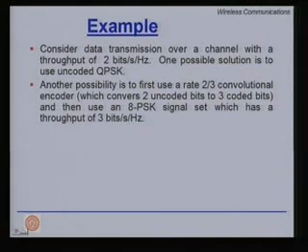If I have done my math correctly, then the advantage gained by coding will more than overcompensate the loss that I encountered by moving my constellation closer. If that is true, then I can get performance improvement without increasing the bandwidth. If, however, I do not optimize properly, I might end up losing.